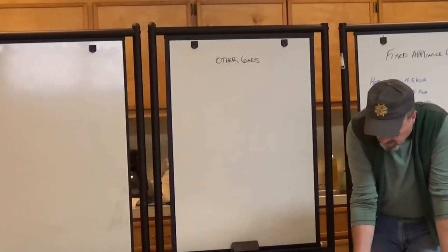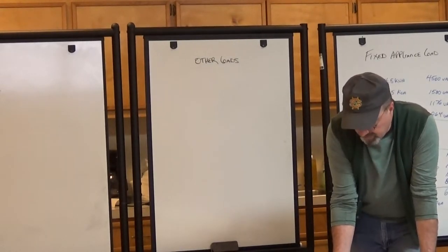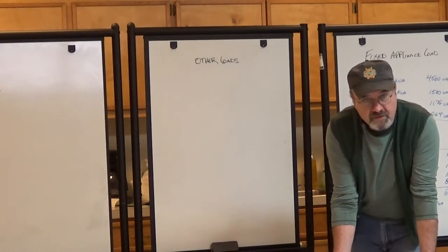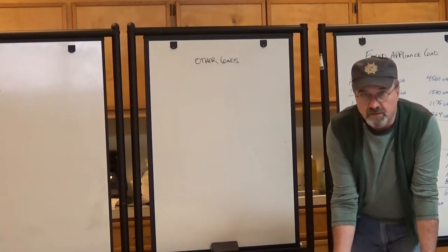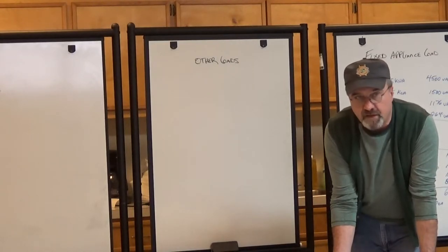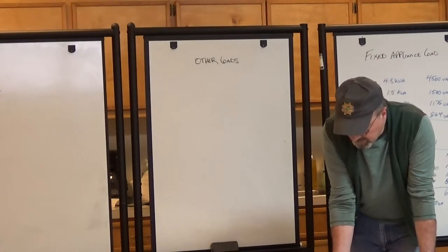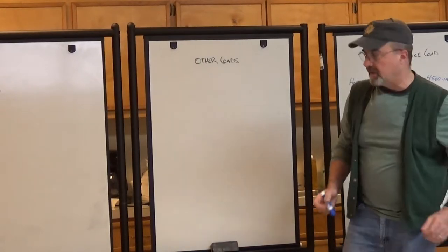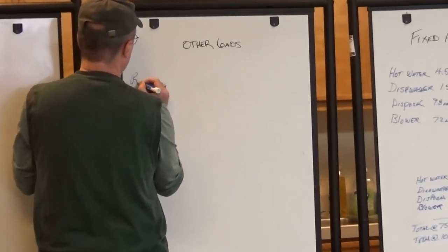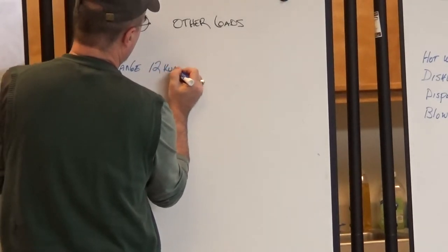So, we have not addressed the range, we have not addressed the dryer, the heat, air conditioning like Austin was mentioning. And then also, we need to consider the largest motor, okay? We have to take an additional 25% of the largest motor. And we'll talk about that in a minute. So, the electric range, what is the range calculated at? 12 kVA. Okay?